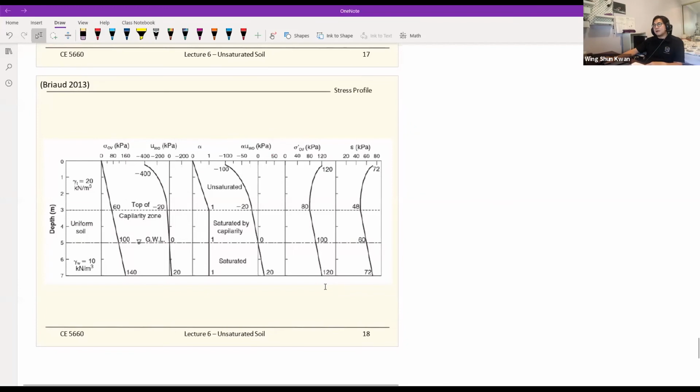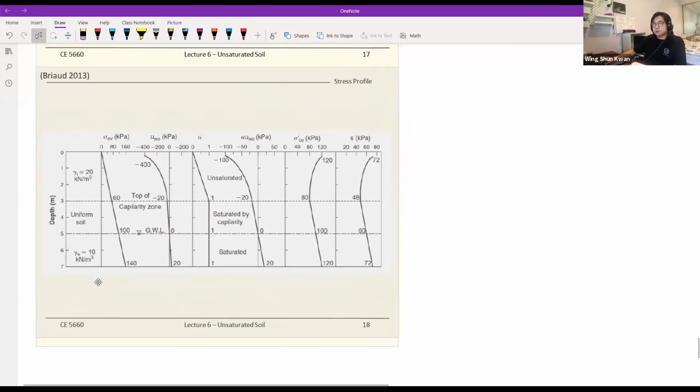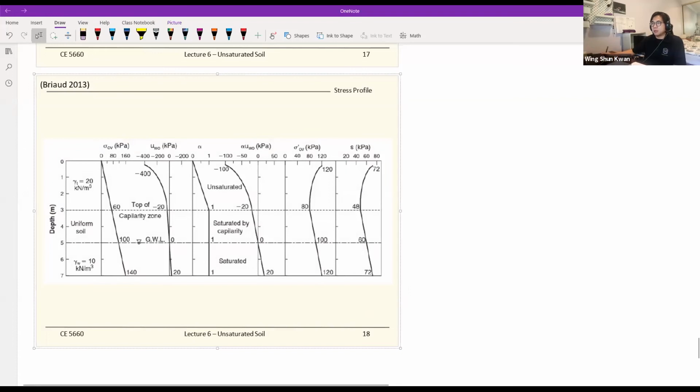Okay, last but not least, back to the basics of geotech. Just like in my undergrad class that I teach, I always emphasize we need to be able to plot or draw the stress profile for the given site. At the undergrad level, pretty much we were just there, with the water pressure. So given a site, for example, you have a soil site here, you have the saturated zone. So you have your saturated zone right here. Pretty much that's where we are in 366.